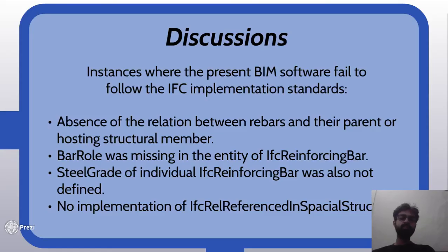Next, if you see, there are some important discussions, like instances where the present BIM software often fails to follow the IFC implementation standards. Like there is an absence of the relation between rebars and their parent or hosting structure members, like we face in the problem with Revit and Tekla. But the users claim that in ArchiCAD we can make the grouping through IfcRelAssignsToGroup, which is quite an impressive thing. I'll be looking forward to that.